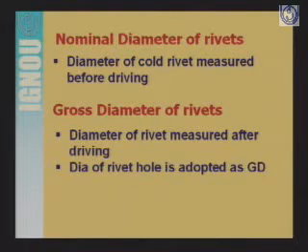Gross diameter of the rivet is the diameter of the rivet measured after driving, and generally the diameter of the hole is adopted as the gross diameter of the rivet, because ultimately that hole has to be filled with the rivet, because the rivet will occupy the whole space of the particular hole driven in any plate for connection.